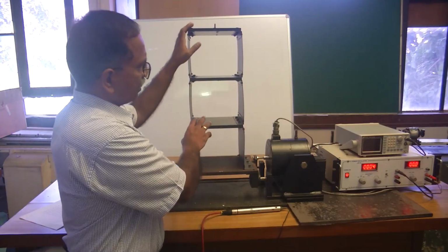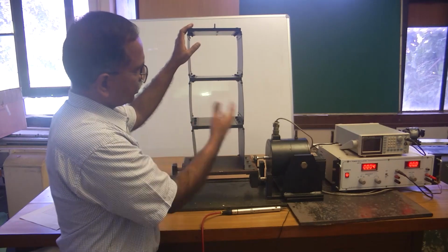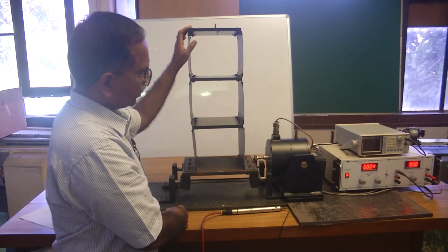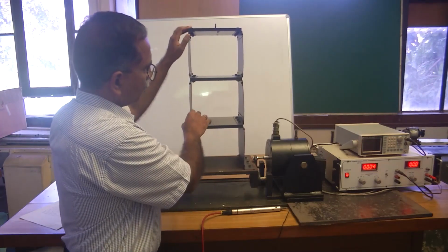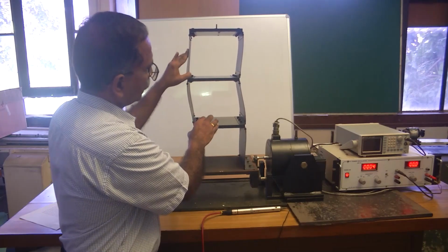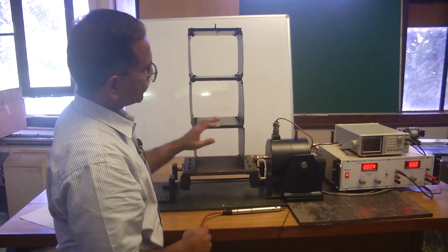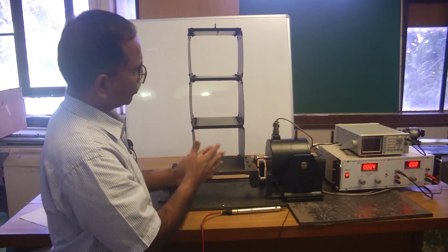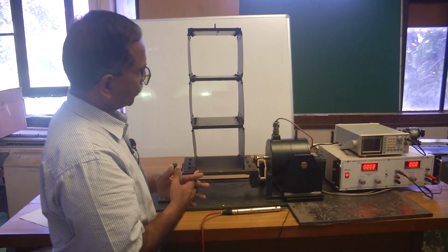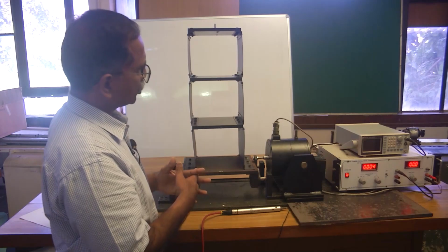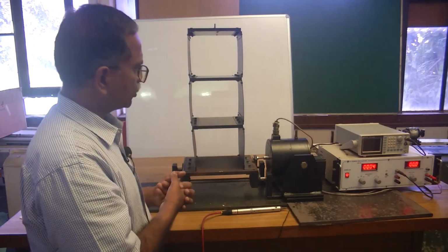Okay. Now, as I said, it's relatively tough to excite all the subsequent modes. Maybe the first mode might be easier to excite. So, therefore, you can see that this is the first mode that got excited. Getting the second mode or third mode is going to be relatively difficult, because we have to pull and push all these masses in exact proportion corresponding to the second or third mode shape and then release it, which, as I said, is slightly difficult to initiate at t equal to 0, and therefore higher mode shapes are hard to obtain by giving initial displacement conditions.